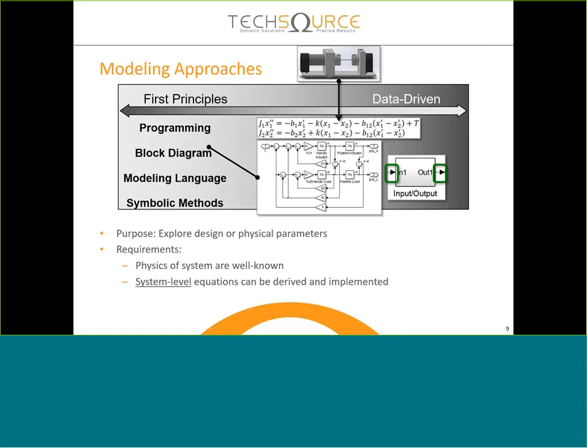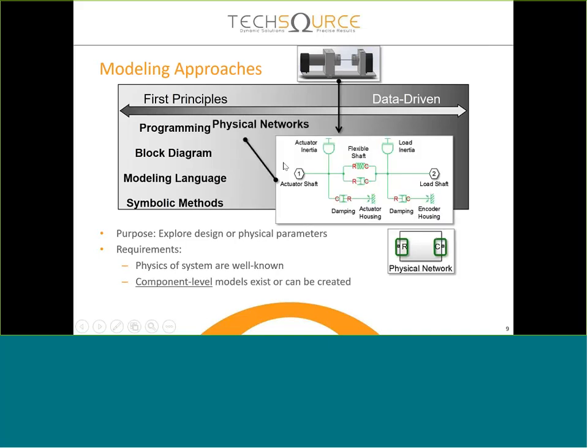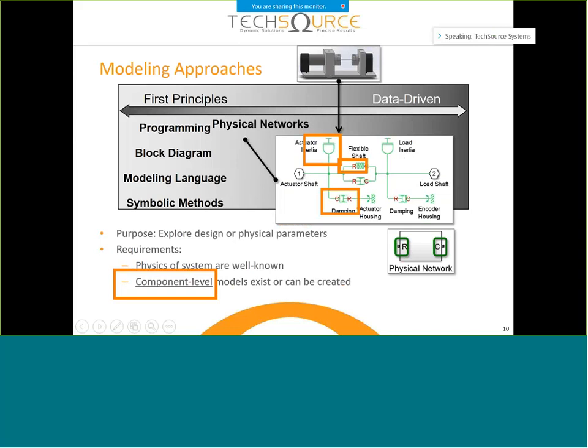And the other way of first principles modeling, if you do not want to use equations, you can use component-based modeling. What component-based modeling is that instead of using equations, you use components. For example, in here, just now we modeled it in terms of equations. Now we just connect your damper, your resistor, your mass, etc., and connect it into the line. This is supported in Simulink by what we call a physical modeling product.